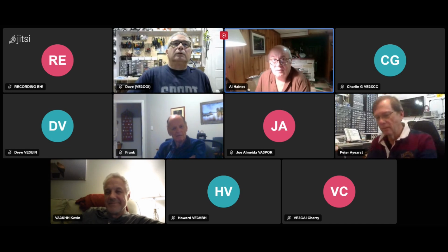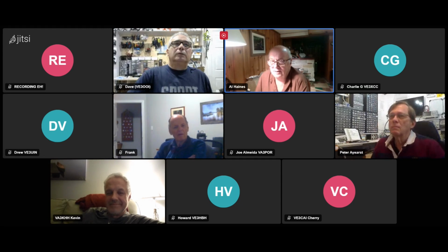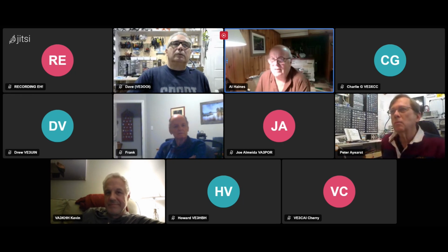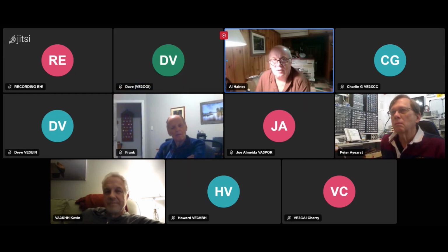Good evening. Well, not a whole lot. Work's in the way, life's in the way, but I'm doing more repair work than anything else. I just finished this weekend repairing one of those Tivoli radios. They have an Achilles heel where the tuning capacitor is one of those polyvaricons, and they wear out. And then when you turn the knob, all you get is static. So I was able to find something in China and soldered it in. A little bit of, I'll say, open heart surgery, but it actually worked.